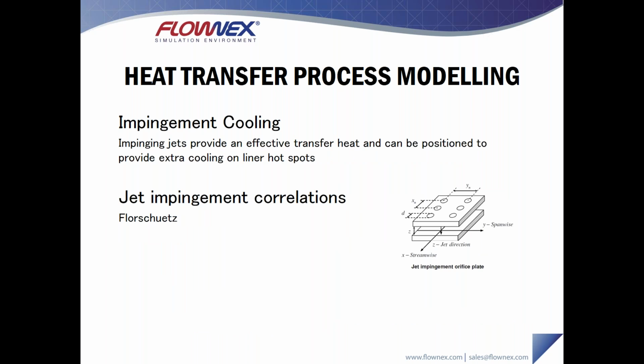Impingement cooling. So impingement jets typically provide an effective mechanism for heat transfer as well, and can be positioned to provide extra cooling on liner hotspots. There are one or two correlations for that implemented within Flownex. Again, those are pretty standard correlations for the gas turbine industry.